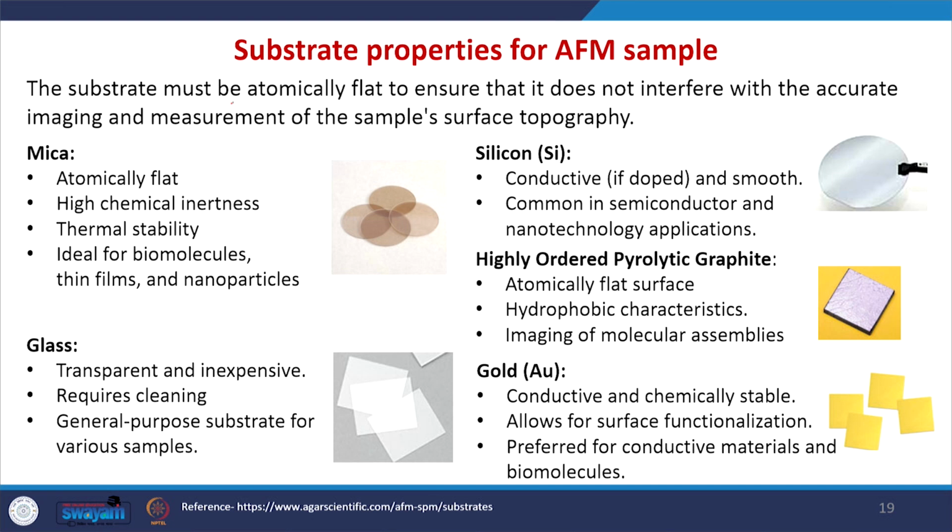Let us see the substrate properties for AFM sample. The substrate must be atomically flat to ensure that it does not interfere with the accurate imaging and measurement of the sample surface topography. So, depending on your sample, you have to select the right substrate. For example, we can use mica for biomolecules, thin films and nanoparticles, and most labs use glass for various samples. It is very easy to prepare a sample for AFM using glass, and depending on your application, we can go for even a silicon substrate if you are working on semiconductor materials.